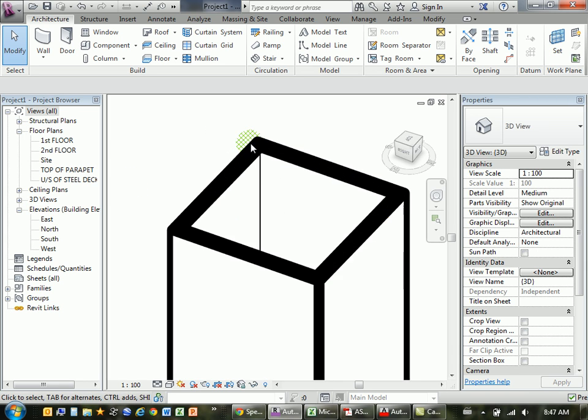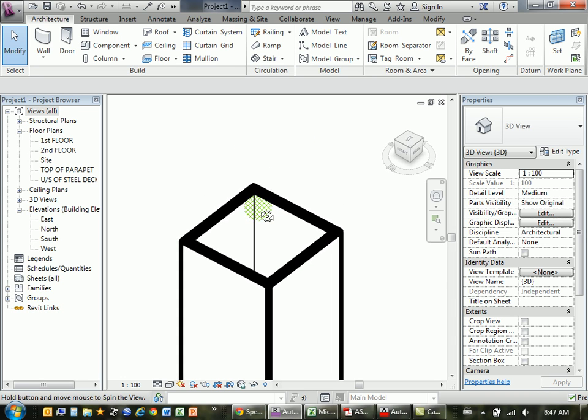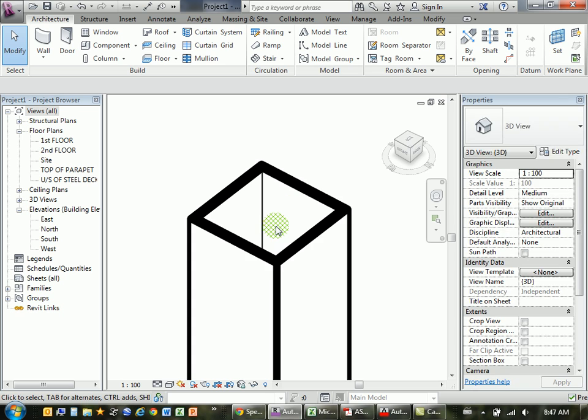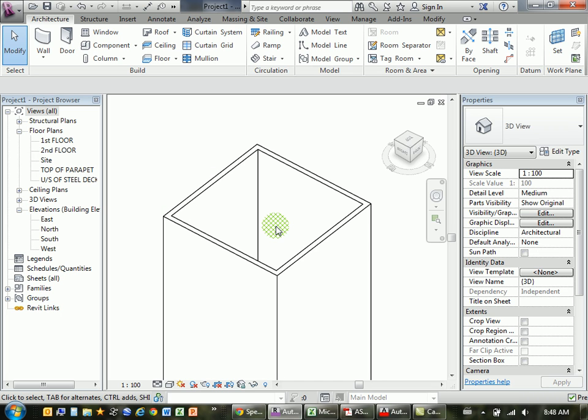The other thing I would like everybody to do, so everyone pay attention. I guarantee you if you don't listen now, you will ask this question eventually in the class. So type in TL. Okay? TL. This should be the default in Revit, but it's not. TL reduces those thick, ridiculous Crayola lines to something more manageable.